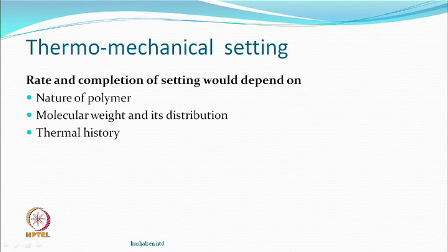Then what happens? Then some changes again in the nature of some crystallization, some disorientation may have taken place before you have texturized and before you are doing a further setting. And so, this thermal history will also matter in the completion of setting, no doubt. The moment you talk about polymer, the moment you talk about rate, temperature will be an important parameter. Like